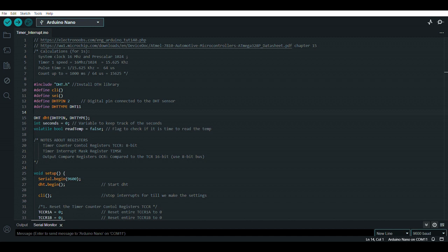Here I'm going to be using 3 applications. The first is our Arduino software, which is just going to be running on the Arduino, and it is going to monitor our DHT11 sensor. Second will be a Python script that reads the serial bus information from our Arduino Nano, and it's going to store that in a CSV file.